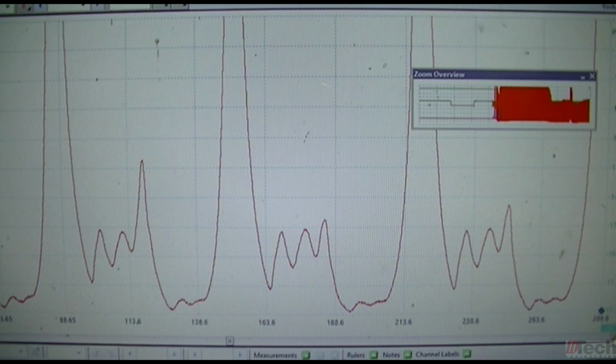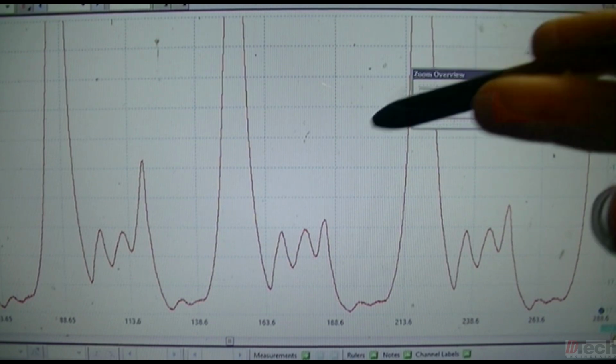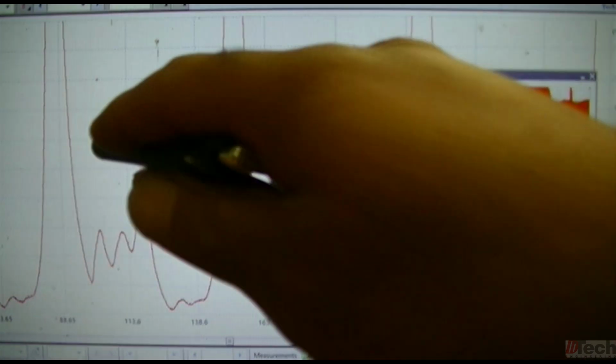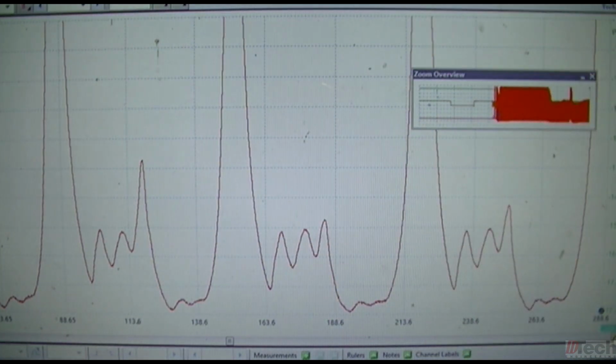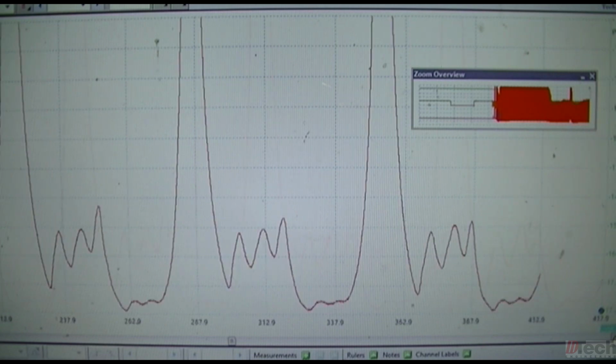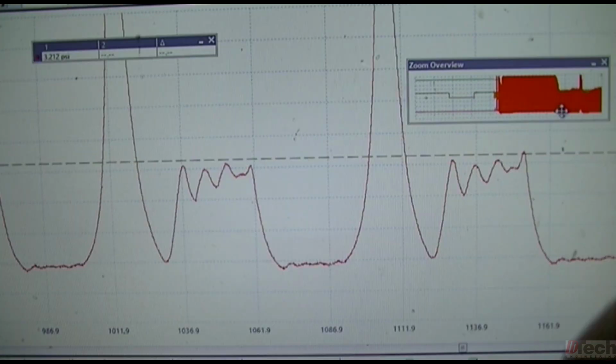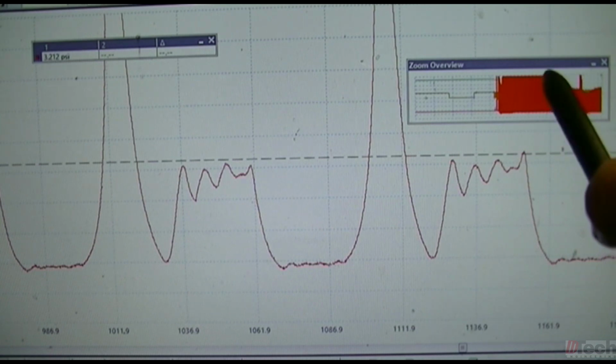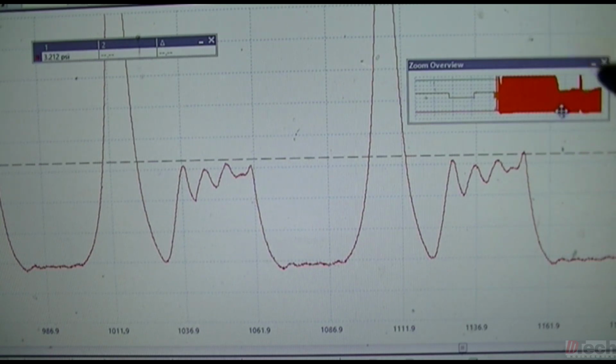I can't tell you right now whether it's happening on the intake side, exhaust side, whichever side. We know we see phasing occurring, which we wouldn't be able to have if the solenoids weren't plugged in, like the last capture. And as we continue to go, now we are at the beginning portion of where it's stabilizing, and we'll continue to scroll.